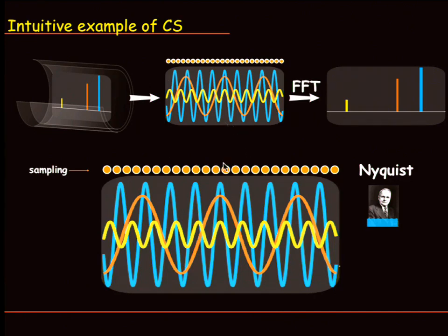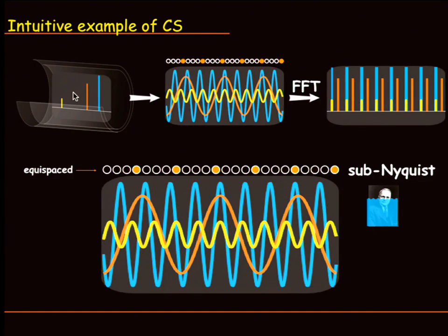Remember that. So that's the difference between the discrete and not discrete cases. But if you think about this as an operation of resampling, so if I have a vector that's already sampled and now I need to make measurements, then if I just compute the Fourier transform of the vector, and I know that its DFT is this, then it would still be the same DFT, because I took the inverse DFT and I computed the DFT back again. It's no problem. Okay. What if I subsample that sequence? I use an equispaced subsampling, which is sub-Nyquist. What would happen then? You go sub-Nyquist.